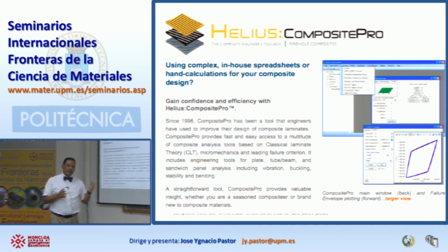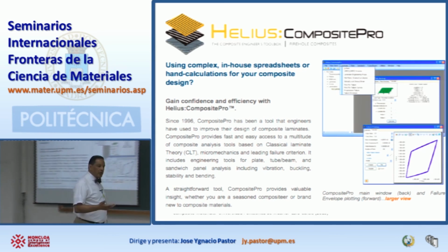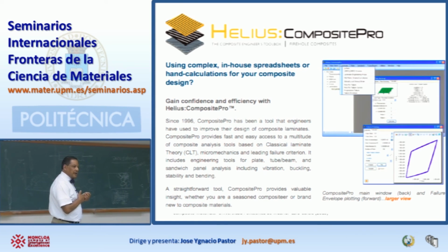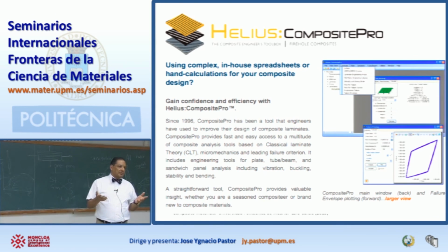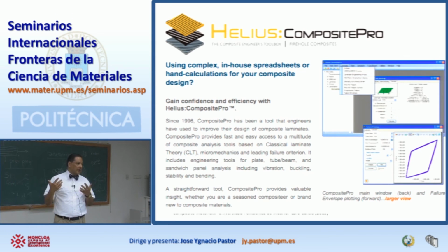Everything comes from understanding that you have highly anisotropic materials, that the properties of the fibers are really the material that enables these composites. If we didn't have carbon fibers with those spectacular properties, we would not be able to do this. We could probably use steel wires or tungsten wires. Tungsten wires are very stiff, but they're very heavy. The density of tungsten is such that you will never fly an airplane with tungsten wires. You will never fly an airplane with steel wires. This is where these carbon fibers really come into the picture. They are so light, and they have some tremendous properties that now you can design these incredible structures.